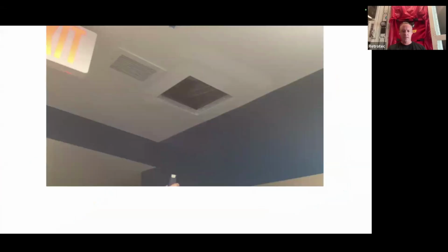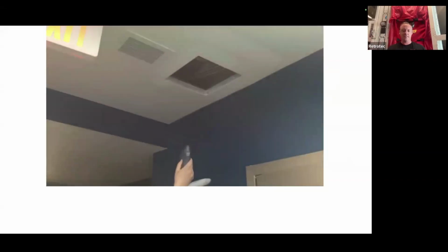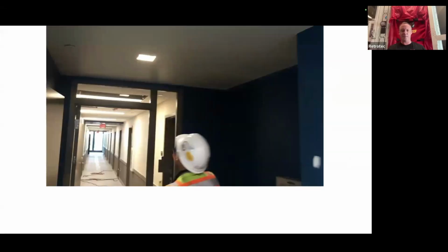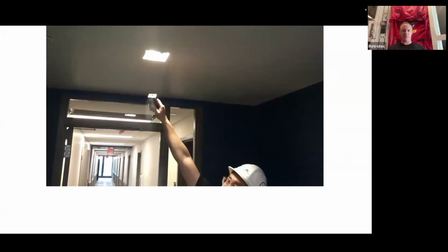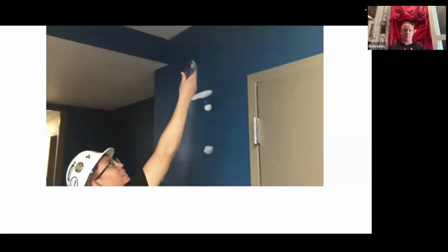So this is a quick clip. This is actually a commercial building that we tested a while back. This is the Tiny S. With this, we didn't need a whole bunch of fog. You can pretty much see what's going on there. The air barrier here is supposed to be the roof. Clearly, they missed a spot. We've got air coming in through a penetration to the drywall that's not supposed to be there. Even though we really couldn't get in there and look around, we can see that there's a problem.